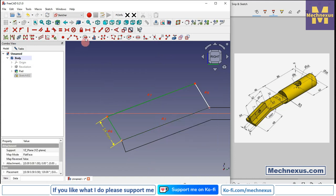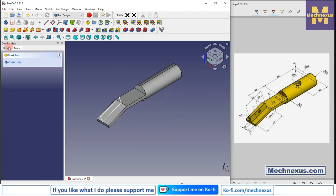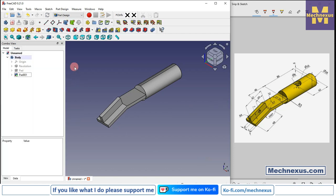Select this and add the perpendicular constraint. So our sketch is fully constrained, and this is of a thickness of 6 mm. So we will come out of the sketch, press V7. Now select the sketch, click on extrude, and this is of 6 mm. So give the value 6 and click here on symmetric plane, click on OK.